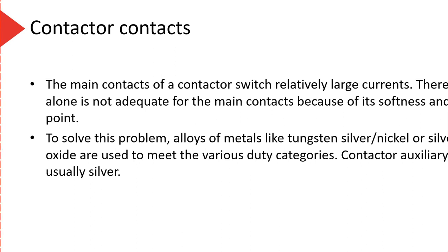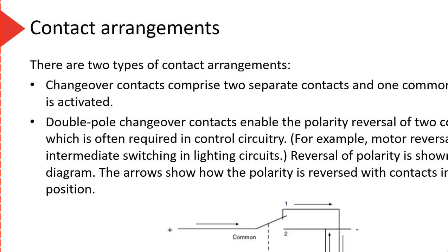However, in saying that, the majority of the time when I've had to replace contacts it's one of two things. One is that the coil has failed, because it's just a little coil of wire. Or number two, and probably more common to be honest, is that eventually the contacts themselves will corrode and fail due to arcing. It just happens. It is what it is. Life goes on. These things will last probably 10 to 15 years of pretty heavy duty operation, opening and closing a few hundred times a day, before they will burn out. They will burn out, but that's a long time and it's a lot of switching. What are you going to do?